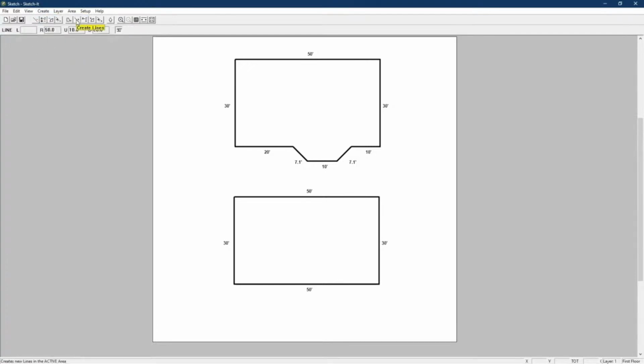We now have a drawing crosshair. Just as when drawing exterior walls, there are a few ways you can draw interior walls. You can free draw them by clicking the mouse to drop the pen and move it around, clicking each time you get to a corner, or you can use the arrow keys. The best method, however, is probably once again using the keyboard to type in the measurements you took when inspecting the house. Move your mouse crosshair near a corner of the house and then press J on your keyboard. This will jump the cursor to the exact corner.